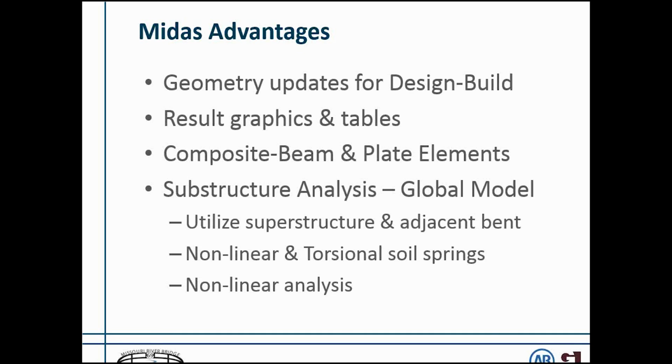Being able to use composite beams is also a great option for modeling in Midas, which we did with our MDX and Midas comparison on our superstructure. And the plate elements that we used for the deck elements to get the right stiffness for our superstructure were very helpful.